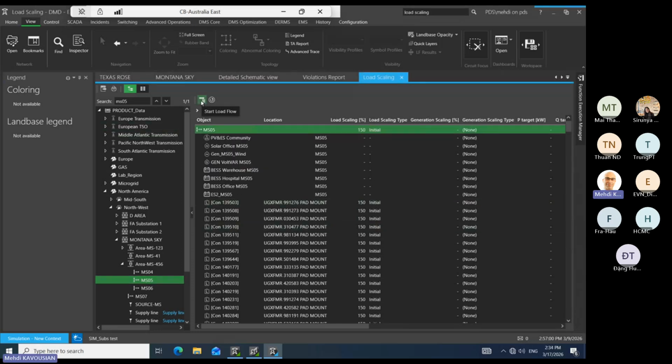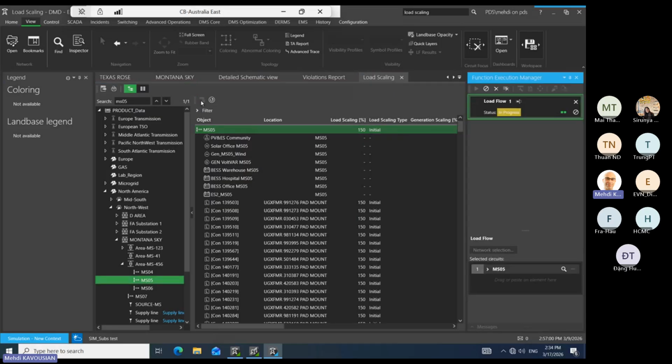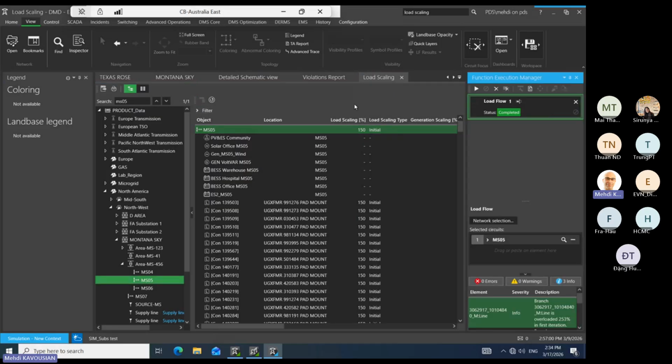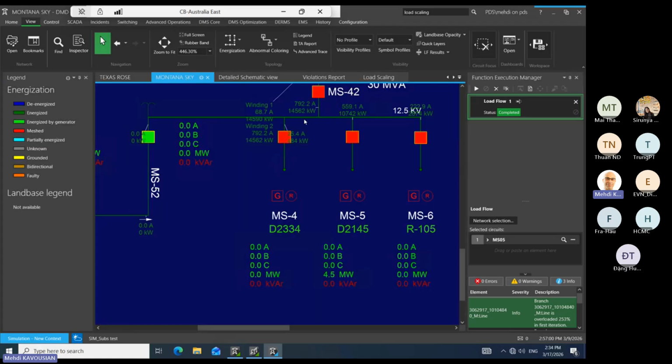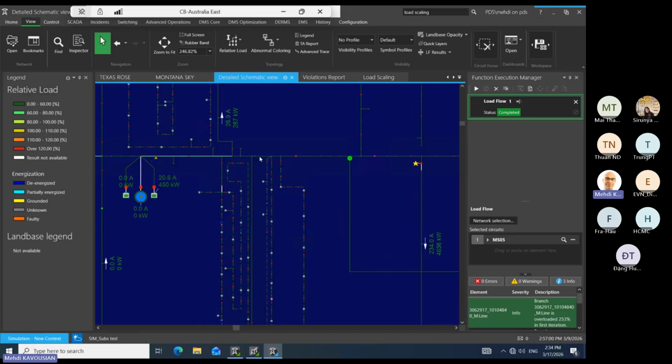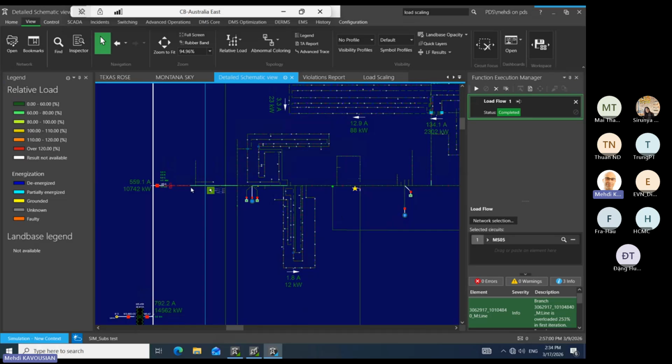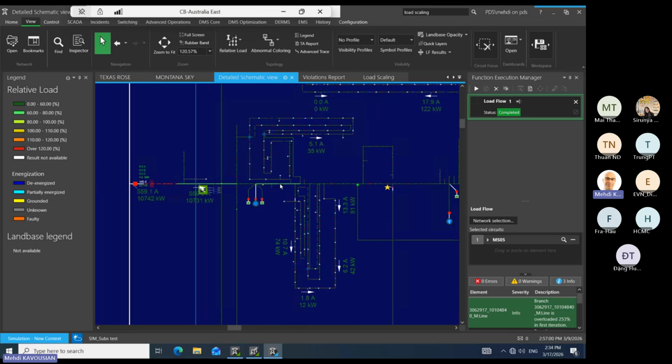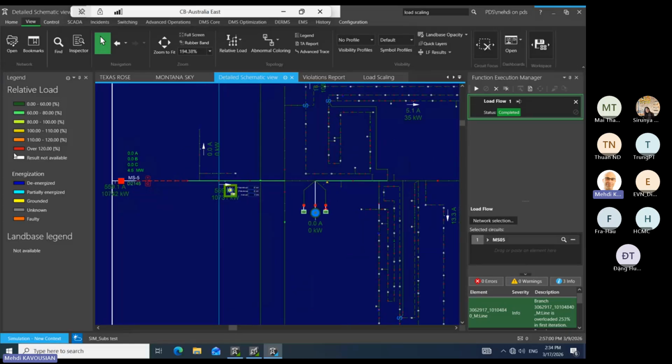And then you run a load flow. There's an icon there, it automatically runs load flow. And then when you go back to this here, if you notice, now instead of 7, it says 10 megawatts, okay? And that result is actually impacted here. You earlier had this one green, and this one was dark green. Now you see, oh, these are in trouble, close to limits, and this one is actually in trouble because you see it is red, it is 120%.